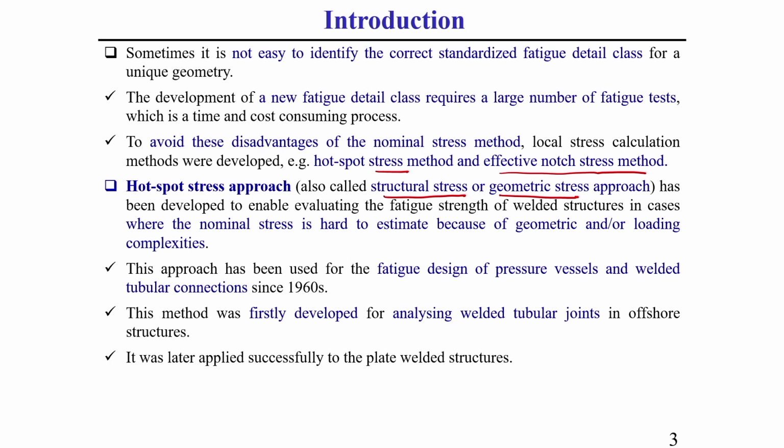It has been developed to enable evaluating the fatigue strength of welded structures in cases where the nominal stress is hard to estimate, as I have already told you, because of geometric complexity or loading complexity.